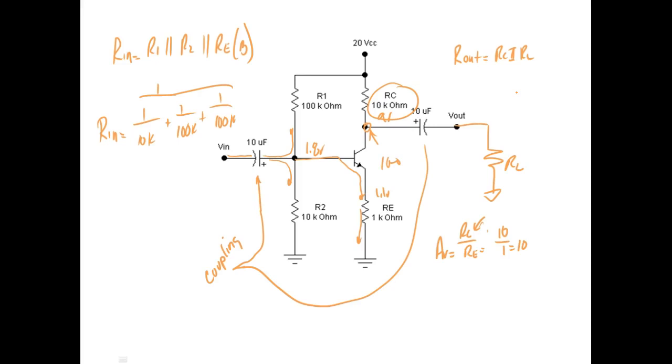That would be useless, having an amplifier if you didn't connect it to something, right? Y'all understand? But the problem is, if I connect a load to the amplifier, then my gain has got to go down because we're loading the amplifier, right? You understand? So the actual formula for calculating gain would be equal to Rc over R out, or Z out.